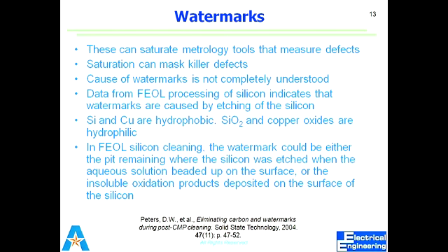Watermarks, as I told you, if you remember, when you were taking your wafer out of that quartz boat, if you blow it dry, it was not at all very clean, the surface was not clean. You were supposed to rinse it dry in clean DI water. If the water dries automatically on the surface of the wafer, you get water marks on the surface, and that is also one of the contaminations. So you don't want water marks, you need to be careful that water marks are never there. Water marks can be there due to many reasons, but the exact reason why the water marks are there